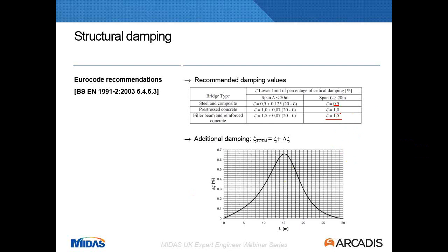Modal integration, what you do basically is extract certain modes from your eigenvalue analysis, and then you use a superposition of these modes to see how your loads excite these different modes.